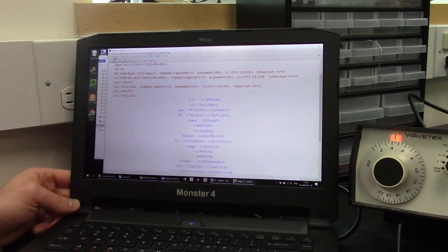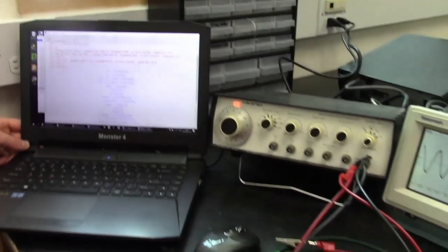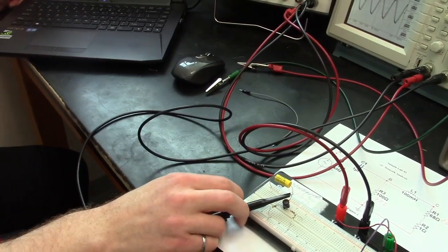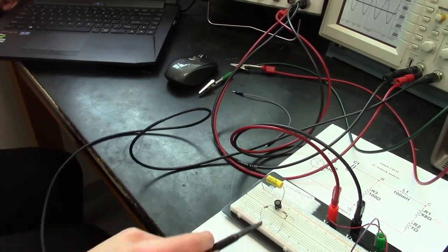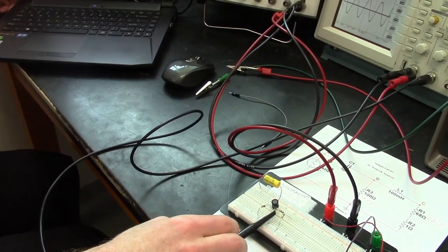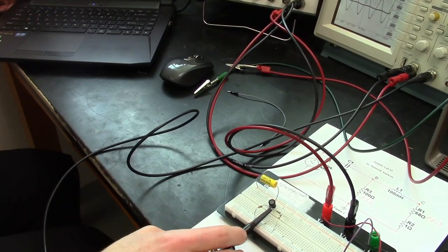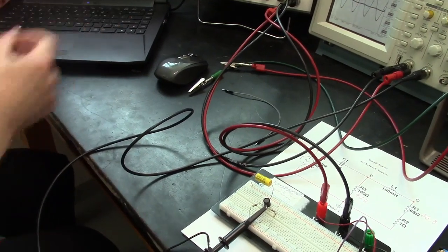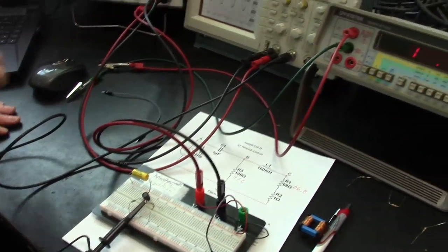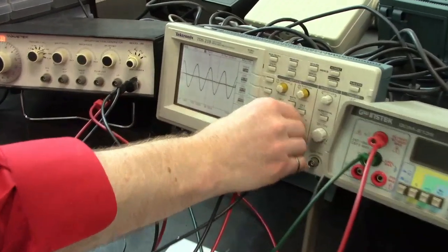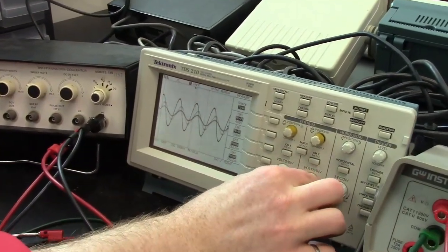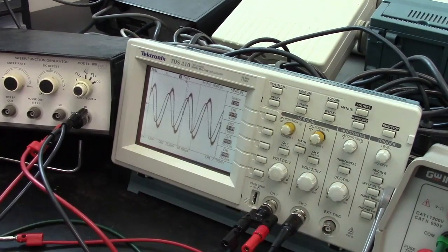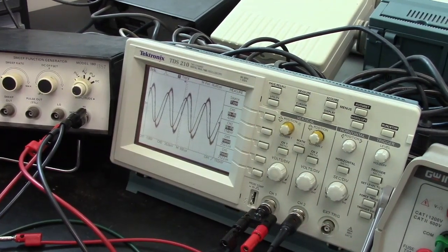If we want to know what the voltage at point C is, then we'll disconnect the scope from there by kind of pulling down on this to release it, and then connect over on the other side of the inductor, and this is now point C. And here the signal's a fair bit smaller, so we've got 240, 280 millivolts. We can rotate this to the right to make the signal big enough to see it. It's a lot smaller of a signal, so it has a fair bit more noise in it.